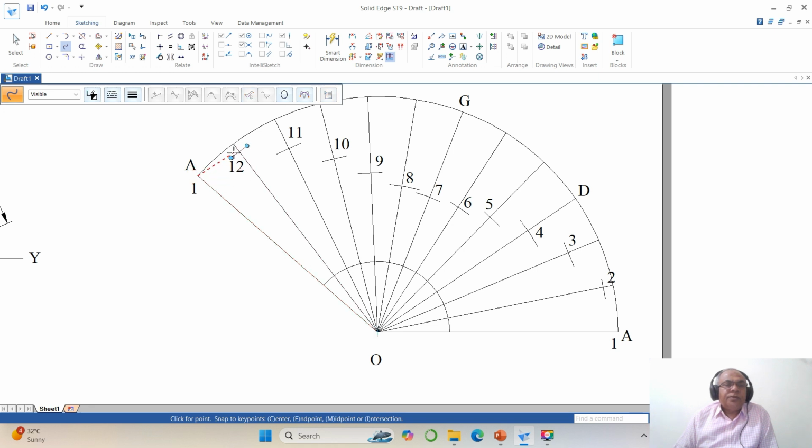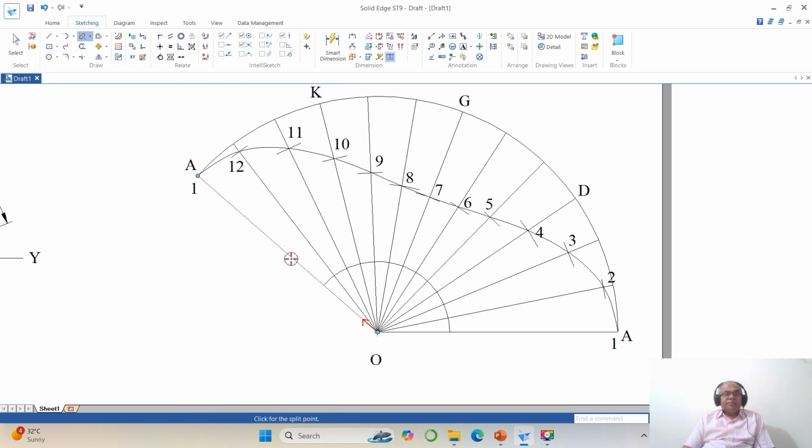Okay. Now you go to curve, take endpoint to this intersection, to this intersection, and so on through each intersection, to this endpoint. Right click. Now we have the split command. Split this line till here, then split this line till here. Now again you go to move command, take this move and keep it here.